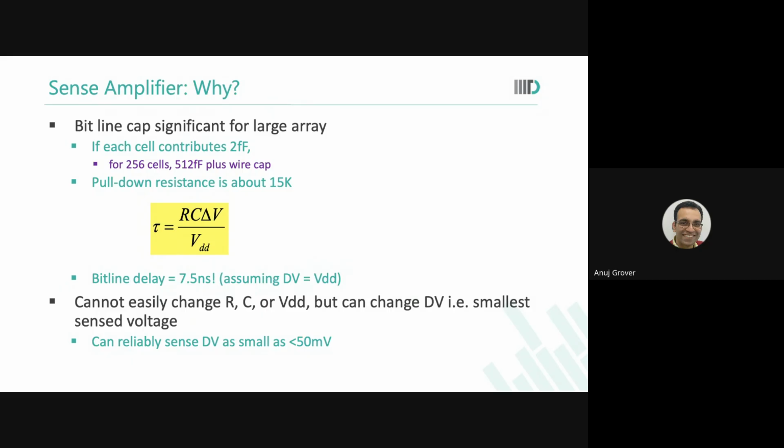Because you're not using a sense amplifier, to get that desired speed you now need to use a 30% larger memory cell, versus using a sense amplifier and a denser memory cell. Are you able to see this? So in those terms, the sense amplifier is a very integral part of memory design. It helps us achieve the desired performance at better density. It helps us achieve better performance at the same density. And it helps us reduce power for the same speed and the same density.